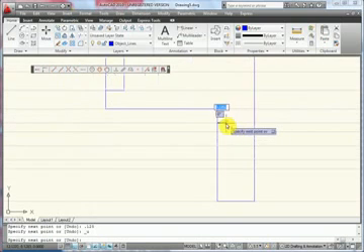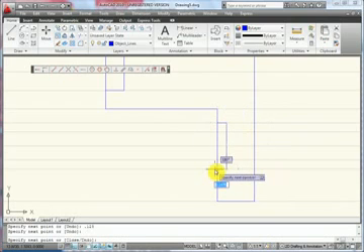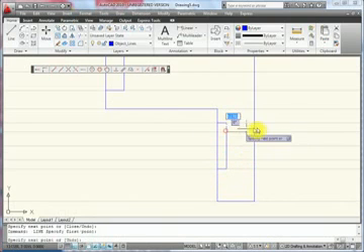I want to make sure that the line darkens in the direction I want to go. If my mouse is up too high like it was earlier, it's snapped in the vertical direction, but I want to be in the horizontal, so I want to make sure I'm over-exemplifying what direction I want to go. So I want to go down 0.125, over and snap one more time in the command, and we'll finish it up with a few more vertical lines.